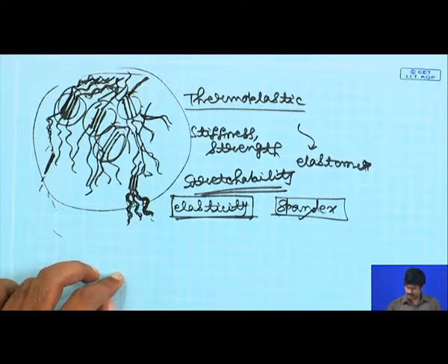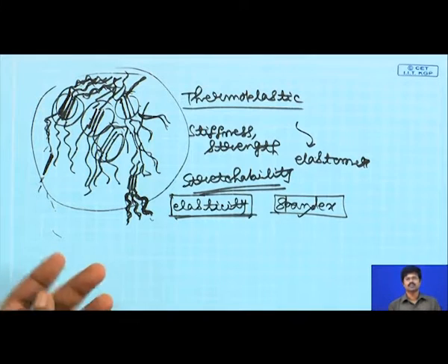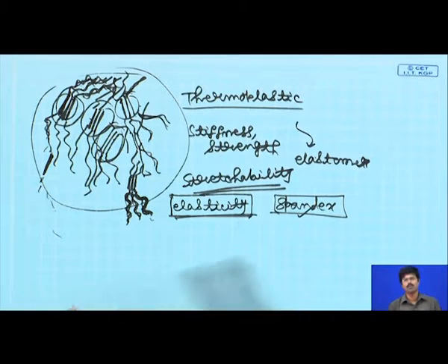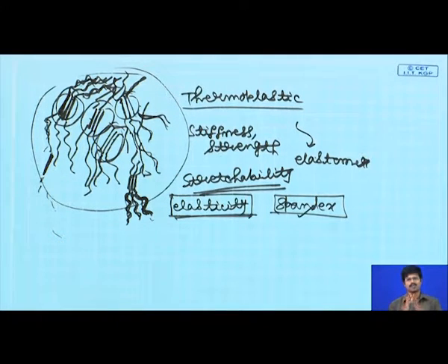All right. So, I think that is more or less all that I wanted to talk about polyurethanes, but one of the other uses also is as foams, because those materials typically, what can happen is that the carbon dioxide can evolve when you break these urethane linkages, and if you suitably process the material, this carbon dioxide can create a lot of volume inside the material, and then you can have what you call a foamy material.